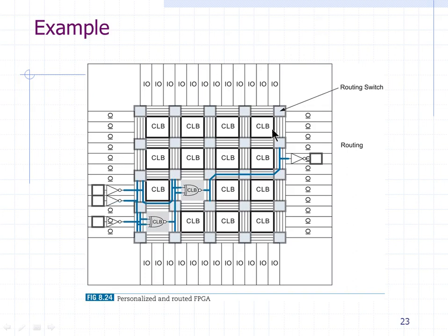This is a cross section of the FPGA. These are inputs and these are outputs here. So a logical path will look something like this. The input is going to some logic here. Then this logic is inside this CLB, configurable logic block. Then it is communicating with some other logic in this CLB block. Then through this interconnect, it is going to the output here. So this is the path from input to output, and there are thousands and thousands of such paths all across the device.